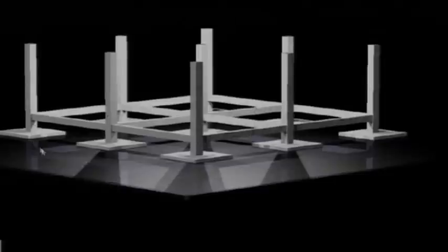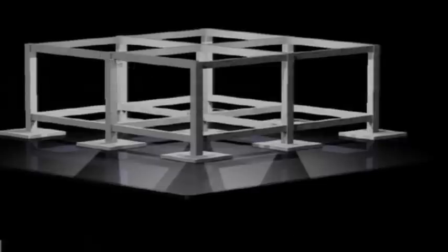We generally do not provide a wall footing for a wall; we start from this tie beam which will take the wall load. We can also take it for the frame, that connection we also consider, but we generally use it for walls.